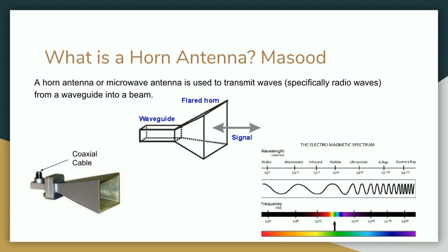As you may be able to tell, the horn antenna is basically a waveguide which flares out. This is because the horn antenna acts as an impedance matcher between the waveguide and free space. By having a tapered or flared end to the waveguide, the horn antenna is formed, and this enables the impedance of free space to be matched. Although the waveguide will radiate without the horn antenna, this provides a far more efficient match.